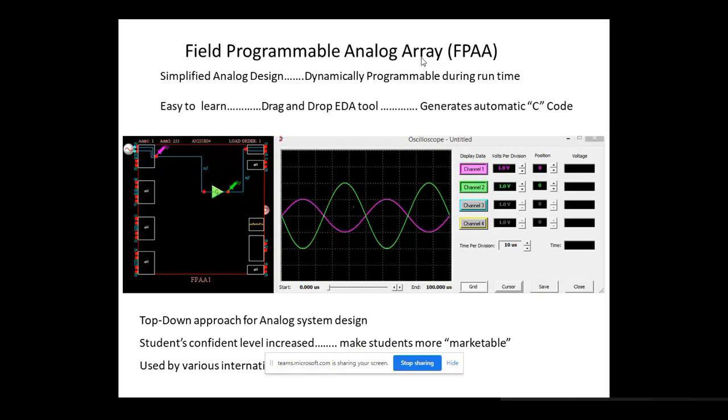Once we have made one system, okay, for example, a simple inverting amplifier, you have made it. Just a simple amplifier. We are feeding one simple signal, a 2-volt DC signal, as an input. And we have made one system that can amplify your input signal and gives the output. So my amplifier gain is 2, and my input signal DC voltage is 2 volts. I'm feeding it to that amplifier stage. Output I'll get: 2 is the input signal and 2 is the gain, so I'll get 4 volts as the output. So my signal will be amplified.